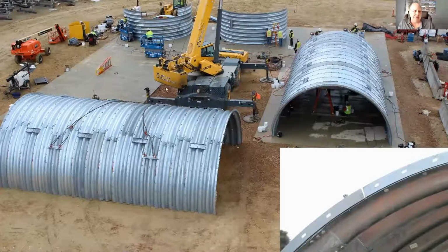So at this site, this structure was about 1,100 or 1,200 feet long. So the contractor actually built a pre-assembly area where he could build a couple of these modules at a time. So that's what we're showing here. He has one that's getting ready to be transported, another one that they're working on, finishing up, and then in the background here, they actually pre-built these in 7.5 or 10-foot wide rings, I think, and then pieced them together. So they had a pretty smooth operation working there. On the bottom right, that's a closer up view of what that rolled angle looks like when it's attached to the ends of one of these modules.